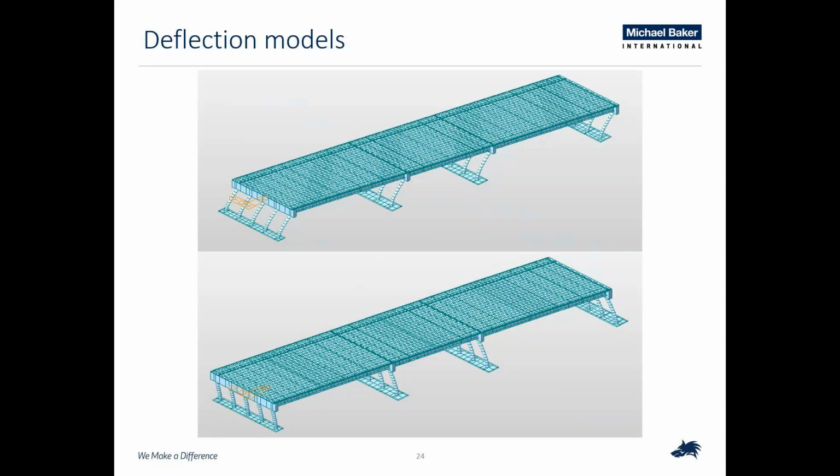after going through and developing the models, this shows both the longitudinal above and the transverse below those deflections. And the deflections that we were getting with this flexible model is 8.79 inches longitudinally and 3.62 inches transversely. And because there were some differences in heights of the columns, throughout the design we were getting some interesting kind of racking sort of deflections and forces in the model.